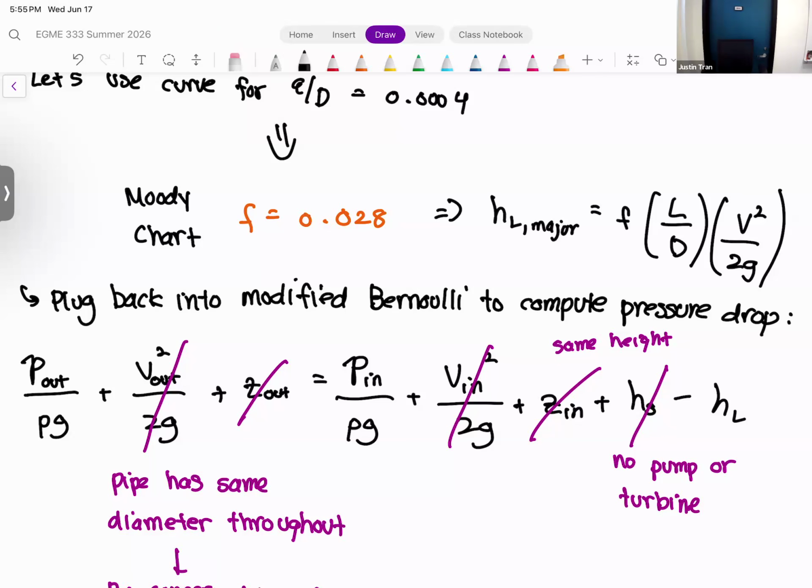Right. So remember, whenever we're using Reynolds transport here, we're computing the force that's on the fluid. But then the force that's put on the jet ski is opposite of that, right? So the force on the fluid is going to the left, negative direction. But then the force that the fluid puts on the jet ski is from the fluid's point of view. Exactly. That's the part that's confusing for people too. When you use this, it's always the force that's on the fluid, and whatever the force on the fluid, equal and opposite is going to be on the solid.